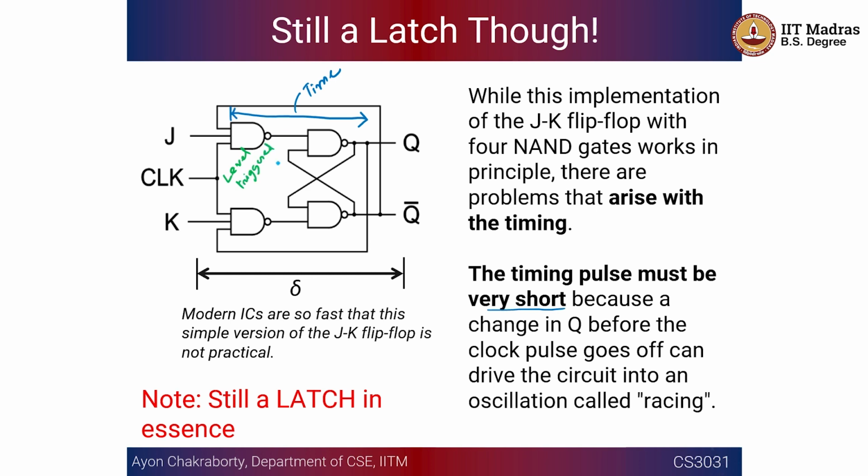Okay, there is some confusion in the terminology and the jargons often, but always remember, if you are using the word flip-flop, this actually denotes a device that is activated on the trigger of the clock or the state change of the clock. It has to be either low to high or high to low or both, but the state change is very important. In case of a latch, it is always whether the clock is low or high.